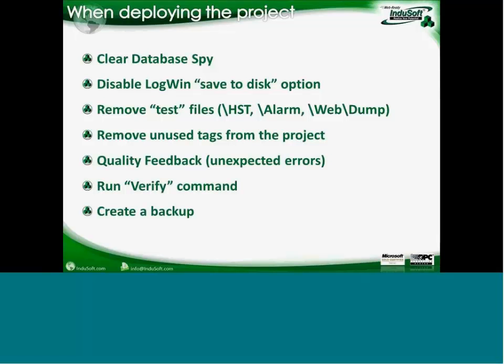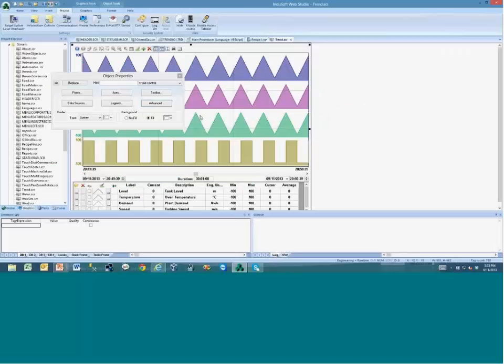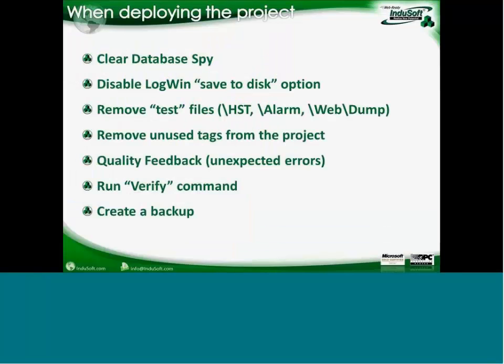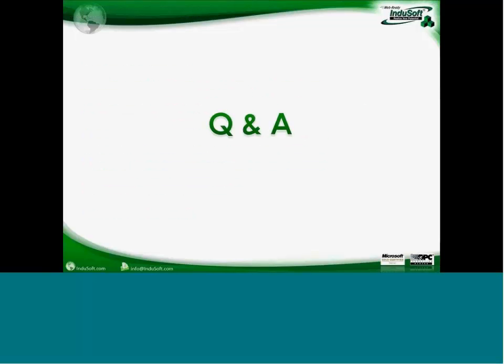And finally, run the Verify command here under the Home tab. Run the Verify command and make sure that in the output window you do not have any errors in your application. Then create a backup, deploy, and hopefully run for a long time. Those were the main tips, tricks, and recommendations I would like to pass to you. And now I will open for Q&A.